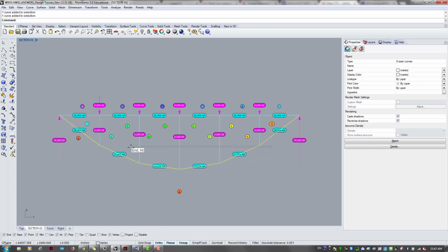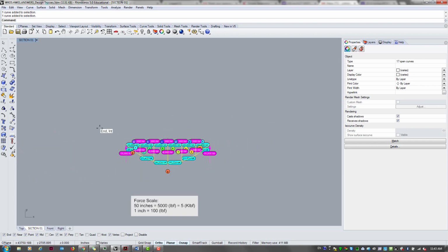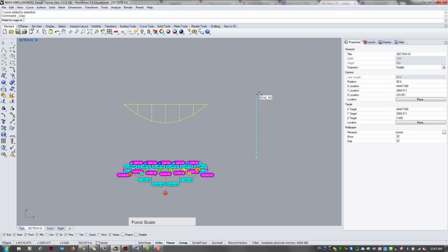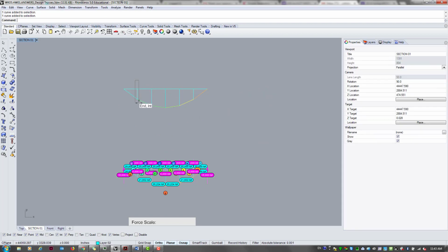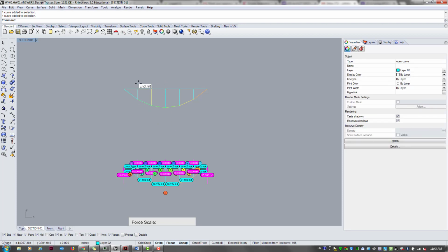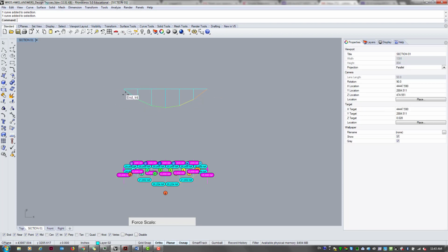A structure like that is very likely to not have a diagonal member because of exactly what we just demonstrated: all the applied force is being transferred to the bottom chord, and the bottom chord is doing all the job by taking this geometrically and structurally efficient form. Therefore, you don't need any of these diagonals.